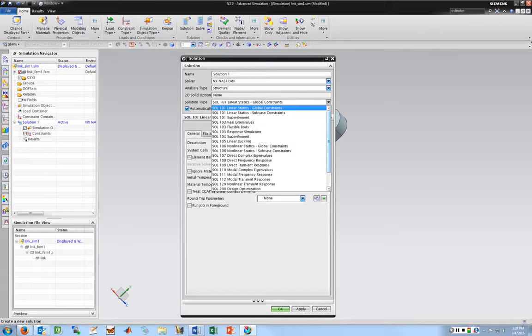So for that, if you want valid results, you basically have to solve out ahead of time what the boundary conditions would be for that to be correct, or you have to make assumptions on it. And it is a linear FEA, so small deformations, and certainly nothing like plastic deformation. If you think you're past yield or well past yield, this is not going to give anywhere near good results.